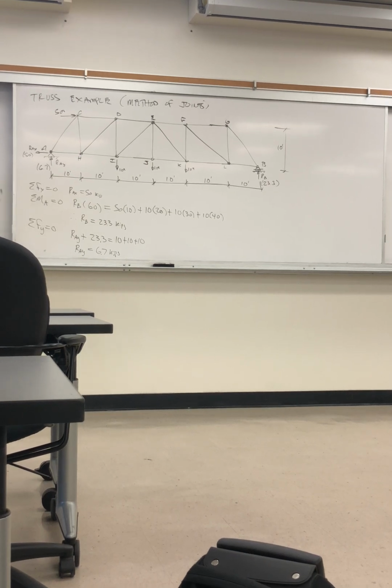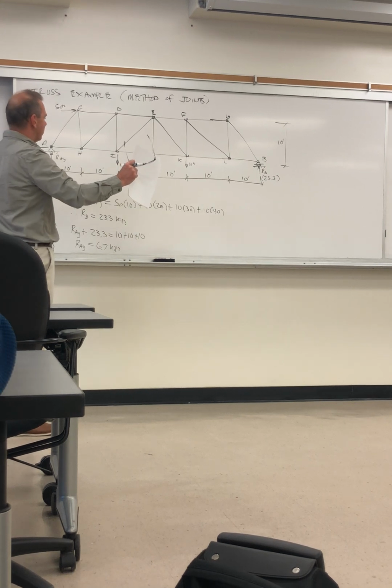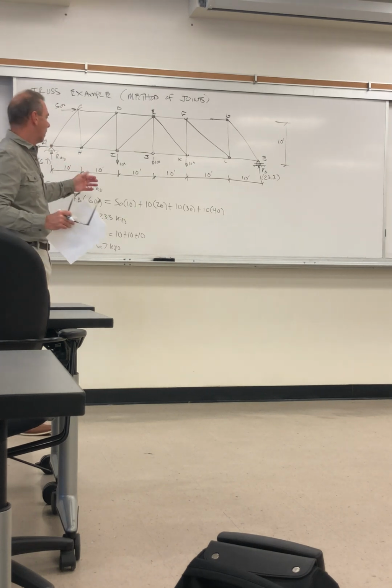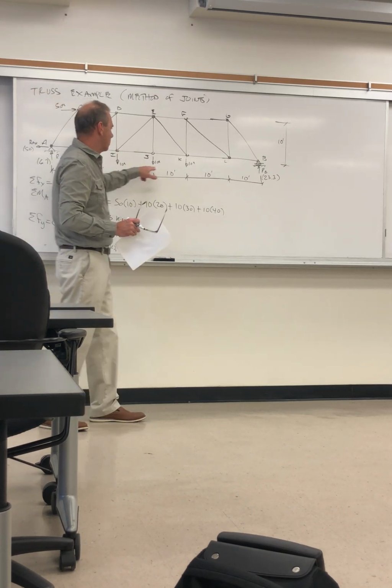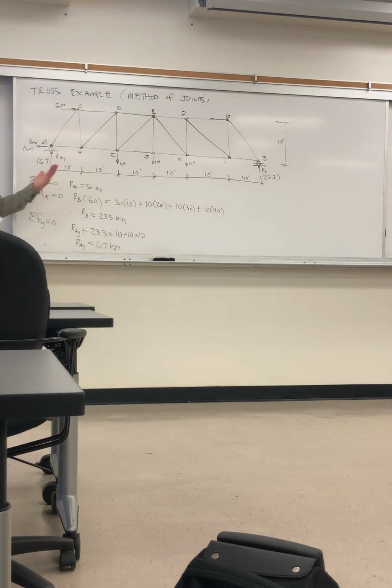Now it's interesting, you can see, just looking at it before we solve for the individual member forces, that the two forces up, 23.3 plus 6.7, is 30, and that is balanced by the forces applied to the structure down, 30. Again, this horizontal force doesn't enter into that, because we're just looking at the vertical forces. Longitudinally, you can see this 50 is stopping the structure from rolling. There's 50 kips applied that way, and it's being held back with 50.